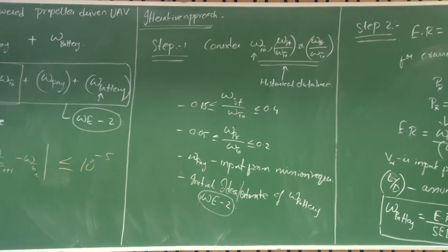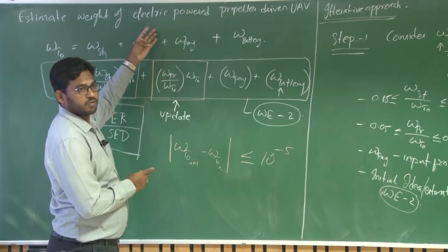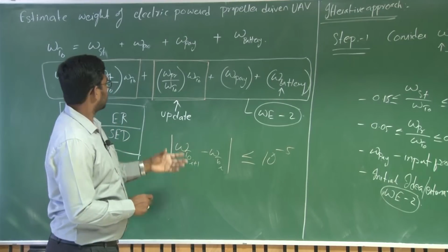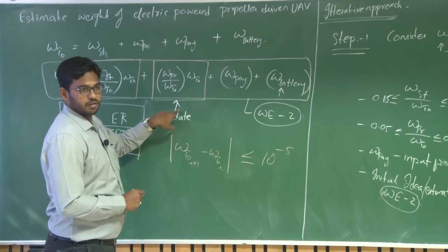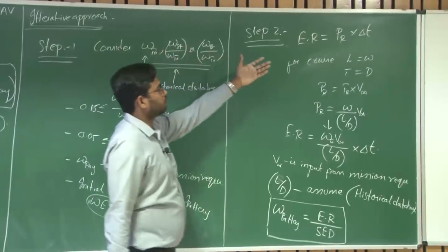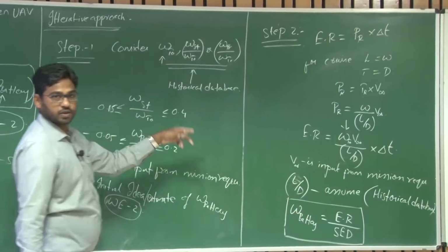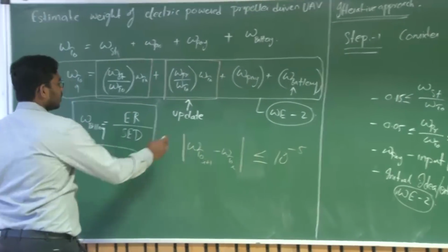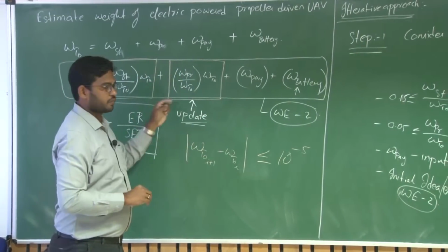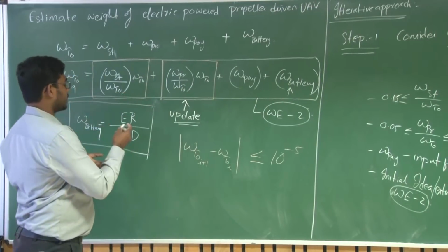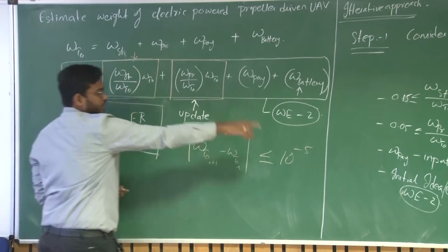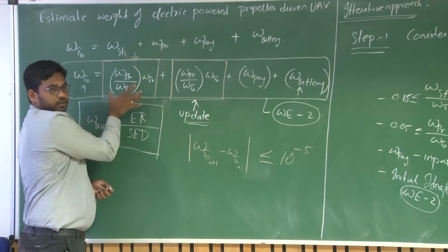See, we are slowly adapting the previous equation for the previous UAV to the current UAV to satisfy the mission requirements, right? Now the power plant is updated, which is selected based upon the power requirement of the system as per the new mission requirements, right? Now you have updated this parameter, right? Again do the iteration, fix this value, and this is again considered as a constant, right? Or the new takeoff weight after this iteration, right? You can consider that as an input here.